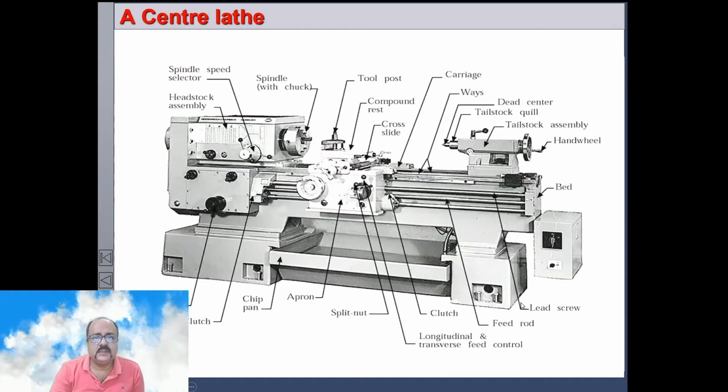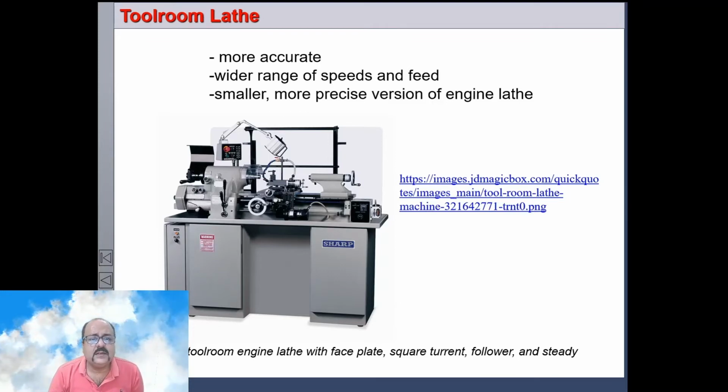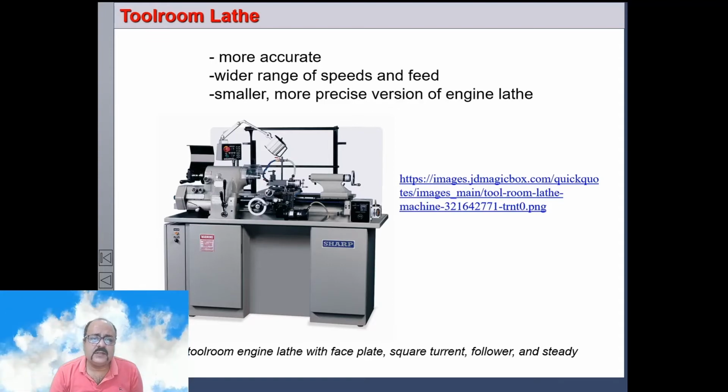This is a centre lathe. This is a tool room lathe. Tool room lathes are smaller in size and very versatile, with large ranges of feed and speed. These are mainly used for making prototypes or tools. That's why it is called a tool room lathe.